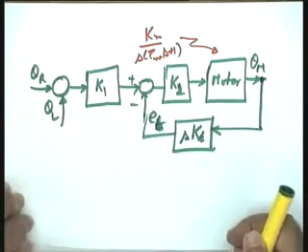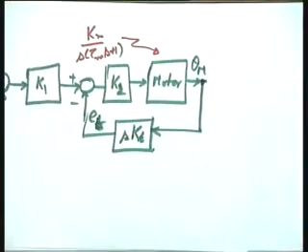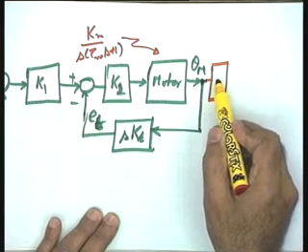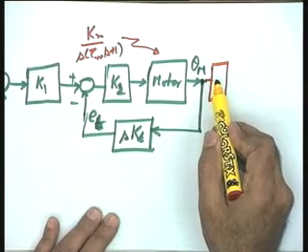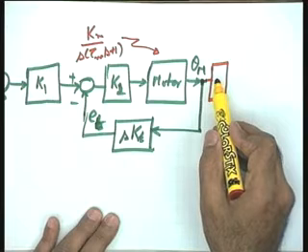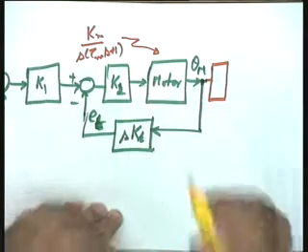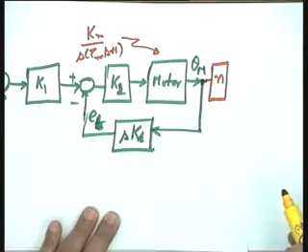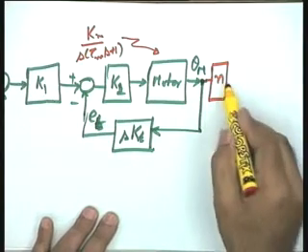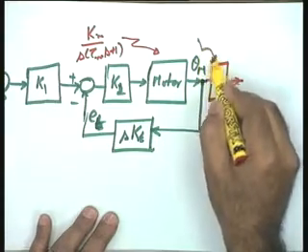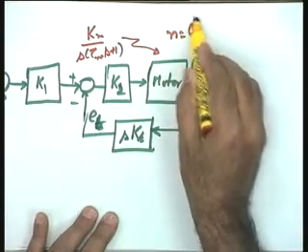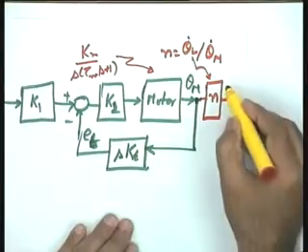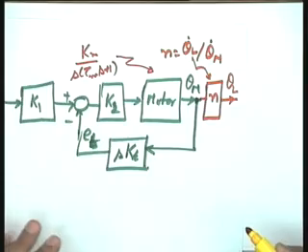Now you want a signal theta L as well. So if I want a signal theta L, give me the value here as well please. N is the gear ratio. What should I put over here? Should it be N? Yes. N we had taken, if you recall, theta L by theta m, that is right, it will be N. I am writing N as theta L dot over theta m dot so that there is no confusion. This is the ratio. If I take this as the gear ratio, then it will be N, and here it is the load position theta L.